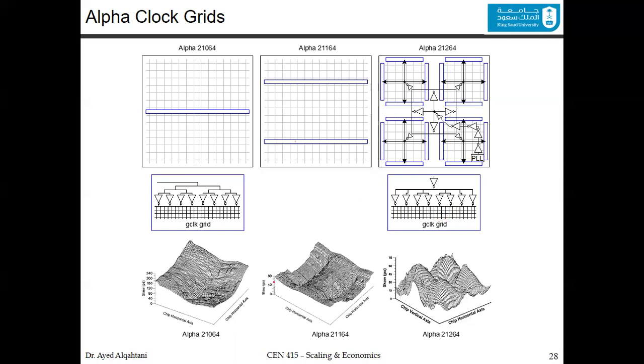That's the idea. Now, if you try to see the chip horizontal axis, meaning the dimension, and you try to measure the skew, you can see it using this idea. The variation in skew is a lot. Since you have these 2 lines here, you can see the effect on that. At the line just below the lines, the skew is minimum. And if you are getting away from it or at the corners here, the skew is a little bit higher. Now using this design, you can see that the skew is peaking at the center since you moved the blue squares to the edges. That's the grid and how we distribute the clock using the grid idea.